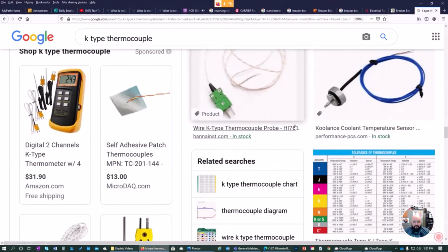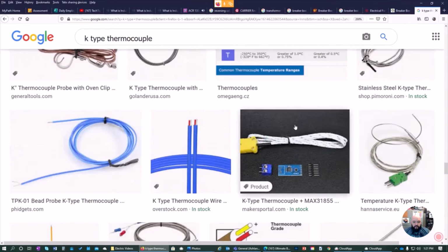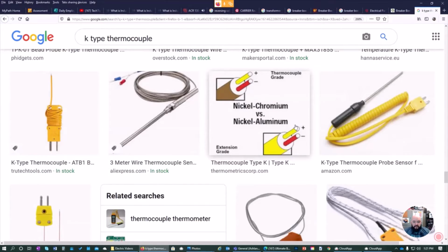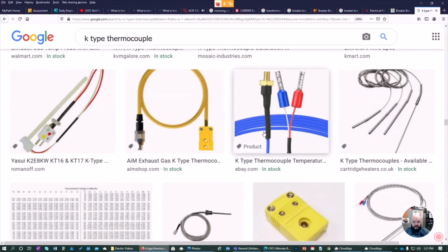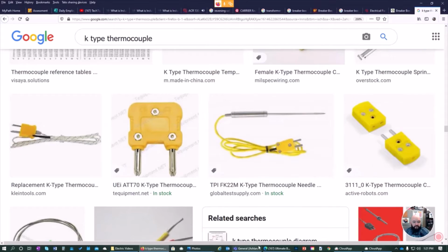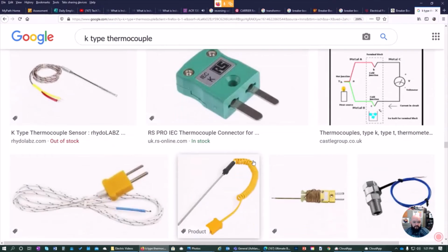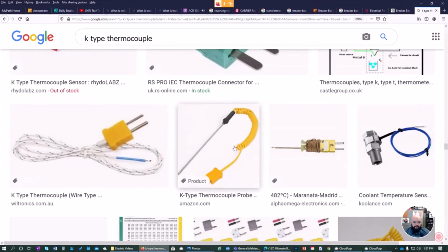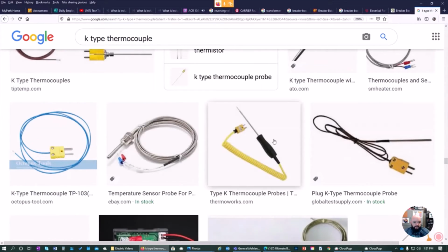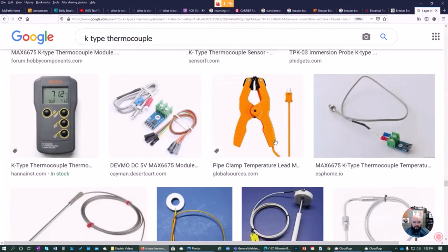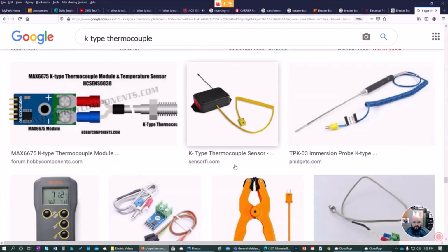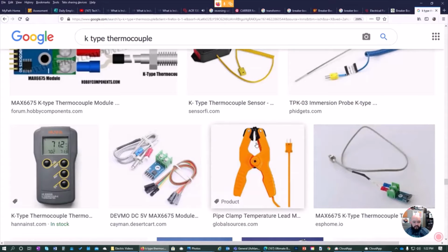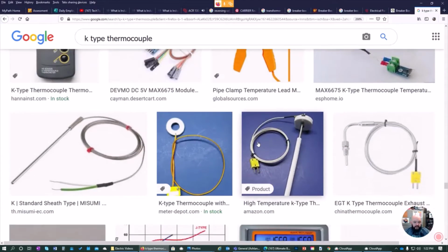And let me find a clamp one. You'll find them on units themselves though. For example, on a defrost controller, on demand defrost, all the thermistors, that's all they are, K-types. If you go back, I'm looking for a clamp. There's a probe, there's a common style. There we go. A line clamp thermocouple. All that is this wire with clamps that'll push it and make good contact on refrigerant piping.